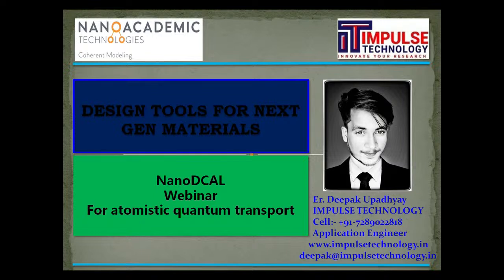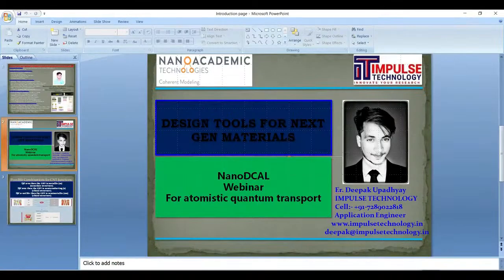Although its accuracy is acceptable as long as structural and cohesive properties are concerned, it dramatically fails in the prediction of electronic and other properties of semiconductors. So to solve this problem, the Hubbard model, DFT plus U, was introduced, which is computationally convenient for accurate calculation of electronic structure. So I would like to open my Device Studio.